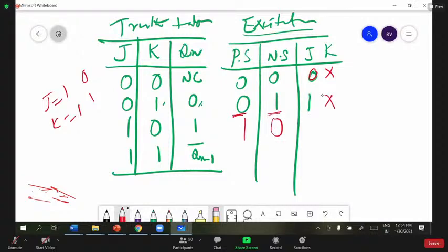Any one of you please tell me, 1 has become 0. What are the JK inputs? 0 1 and 1 1. The first one is toggle. Always remember this, right? Even K equal to 1 and J equal to 0 gives this result. That means the flip-flop resets and stores the 0 bit, right? So this can be replaced as don't care, and I can eliminate this, right?